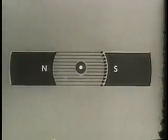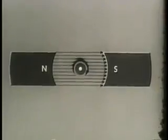In this case, the flow is toward us. The field of the conductor has the same direction as the main field above the conductor and the opposite direction of the field below the conductor. These two magnetic forces added together distort the lines of the main field upward. The field above the conductor is thus made stronger and the field below the conductor is made weaker. So the conductor moves down.